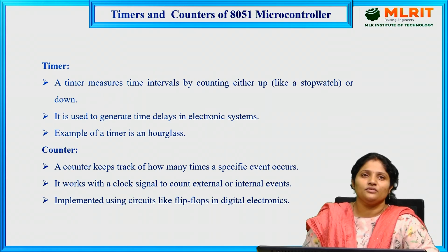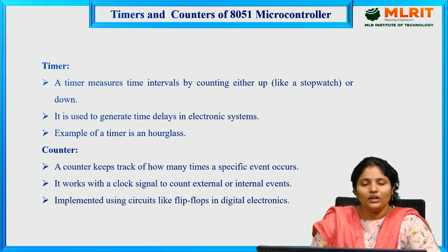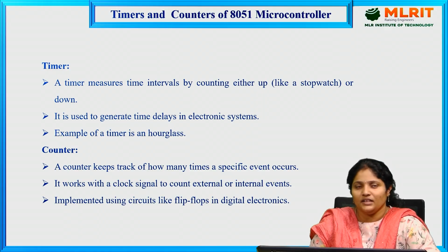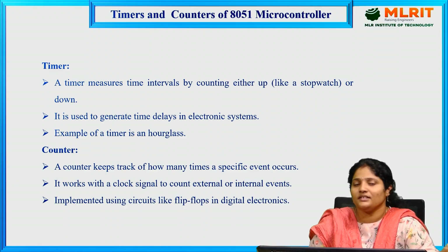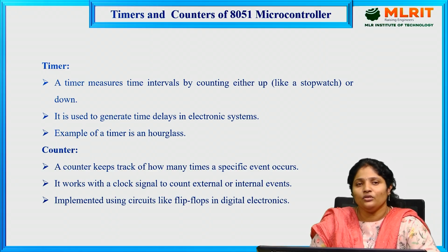So coming to the timers and counters. If we want to provide any time delays in the program, or if you want to count the number of operations done in the external part, or how many times a loop has executed, we will be using the timer and counter unit present in the 8051 microcontroller. So why are we using timers and counters in the 8051?